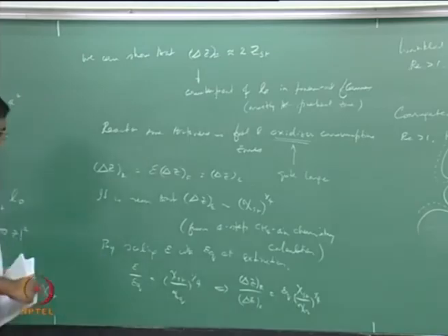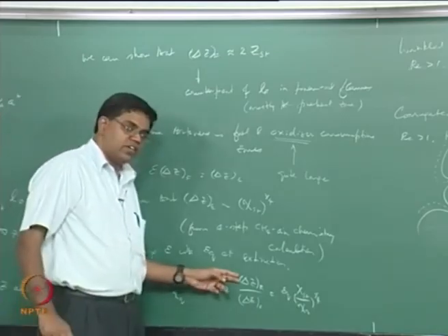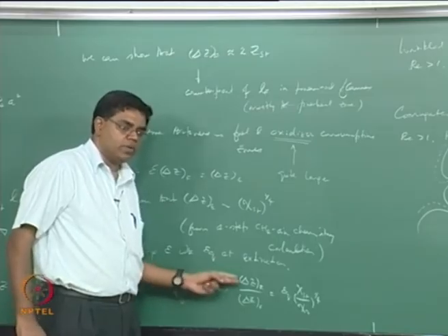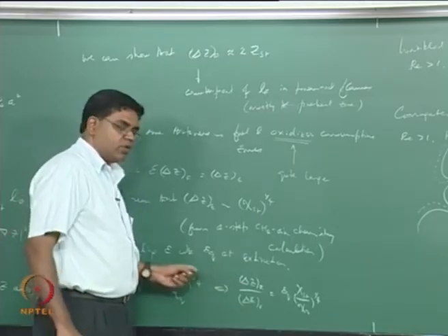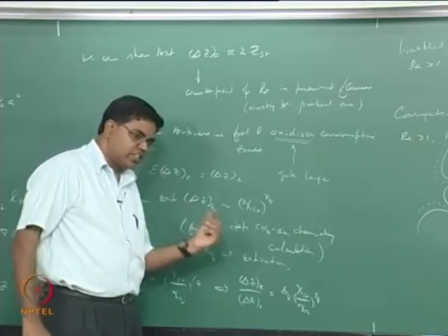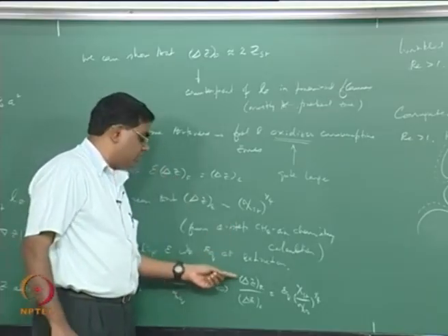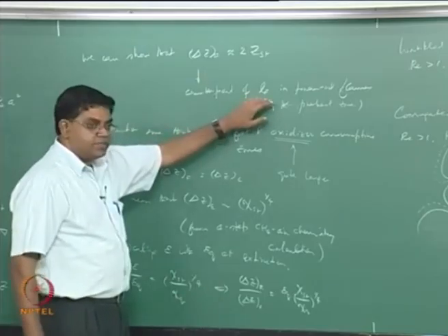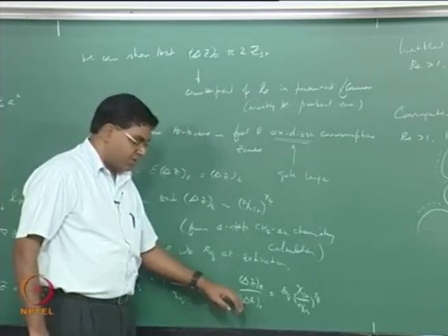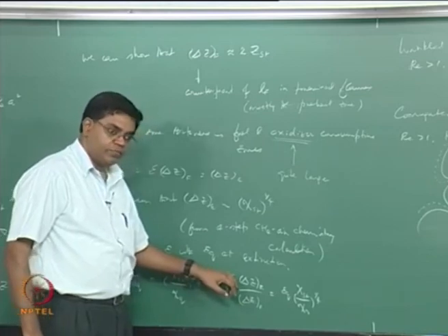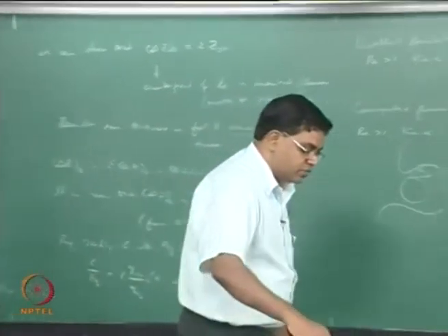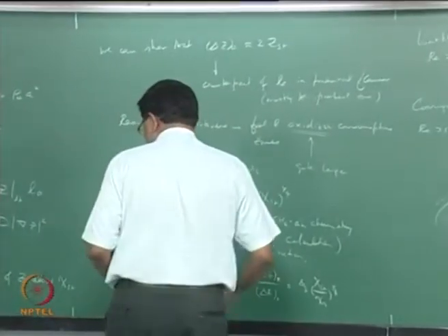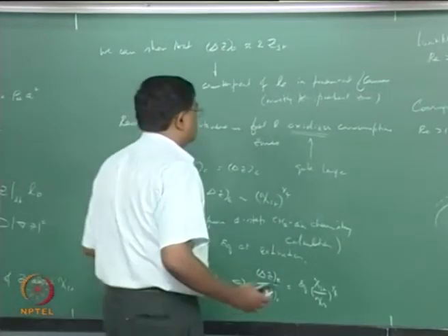Now, the reason why we want to do this is that it gives you L delta divided by LF, the counterpart in the premix flames that we saw, which is the length scale corresponding to only the reaction zone thickness. As I said, this is the counterpart of LF, and this is the counterpart of L delta, from preheat zones. So we're doing something very similar here as what we did for the premix flames.